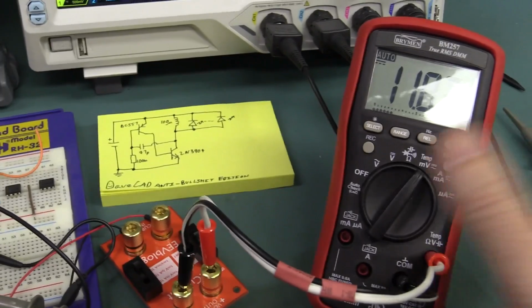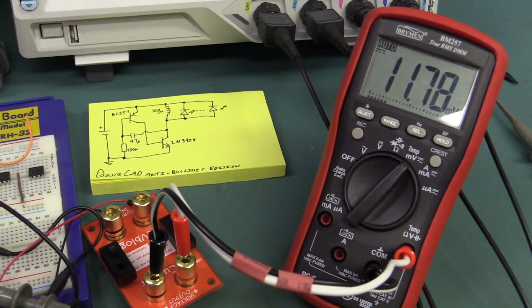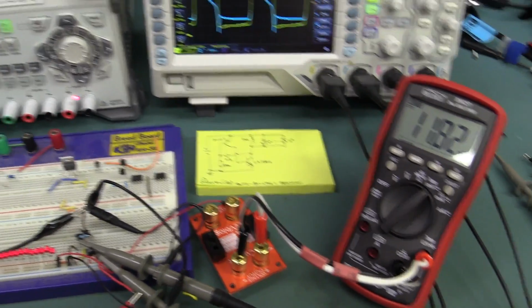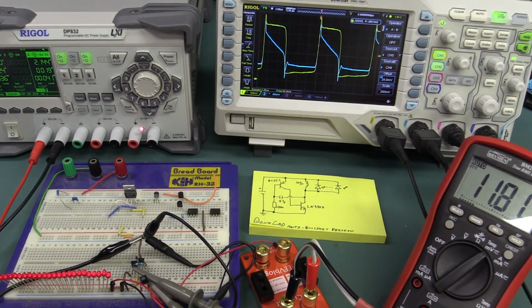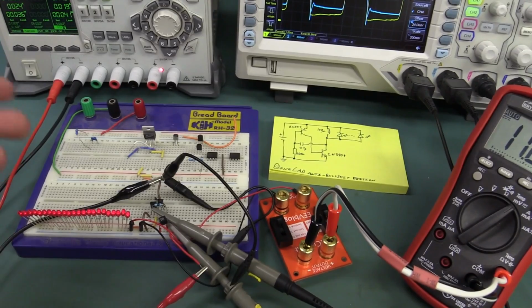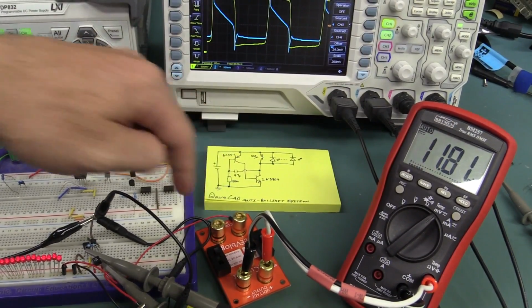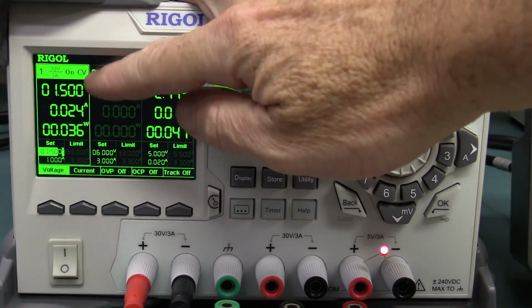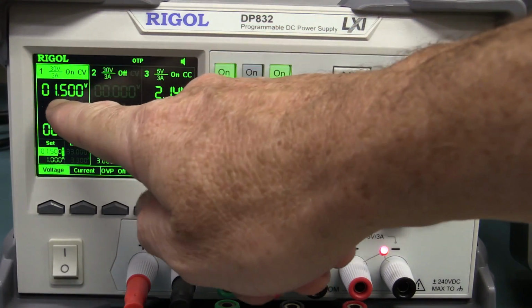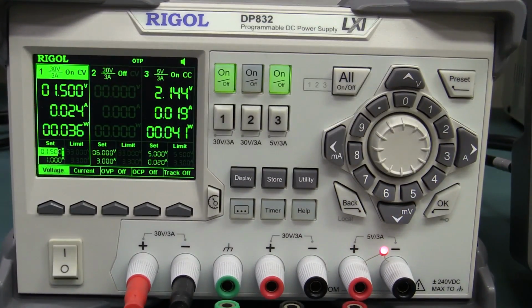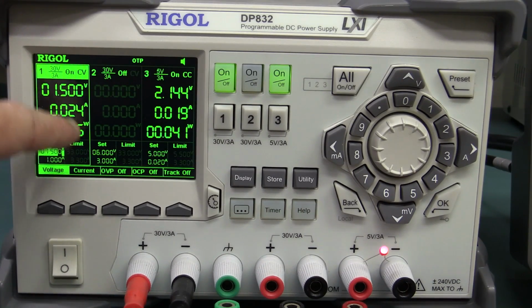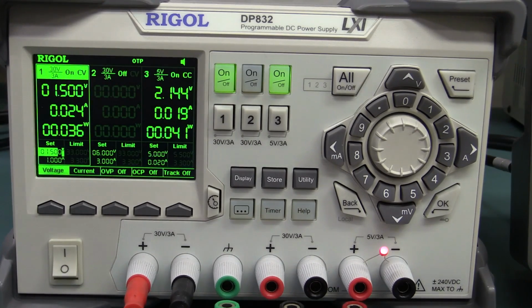And what do we get? Sorry about the lights there, let's round that up to 12 millivolts, which is 12 milliamps, because I'm on the 1 millivolt per milliamp range there. So it's around about 12 odd milliamps taken by the LEDs continuously. And channel 1 here is actually powering the circuit. I've got it set to 1.5 volts, and it's currently drawing around about 24 milliamps or thereabouts, which is equivalent to about 36 milliwatts, which is less than half of what the guy got in his video, because he said he was measuring, as I showed, like 68 milliamps or something like that.